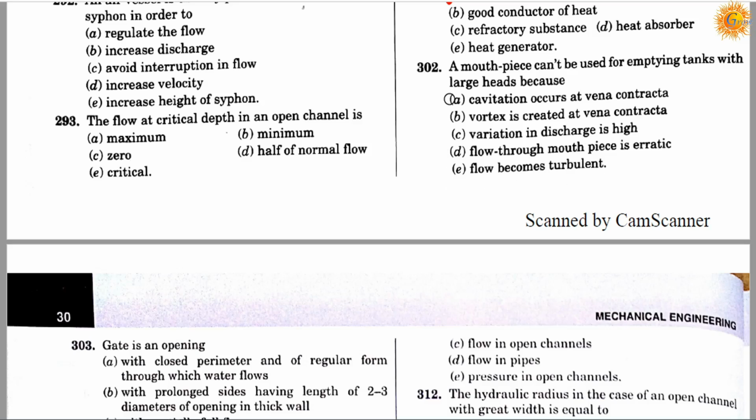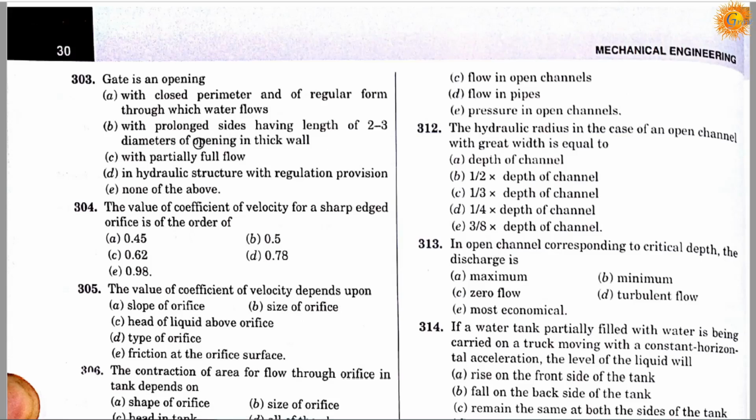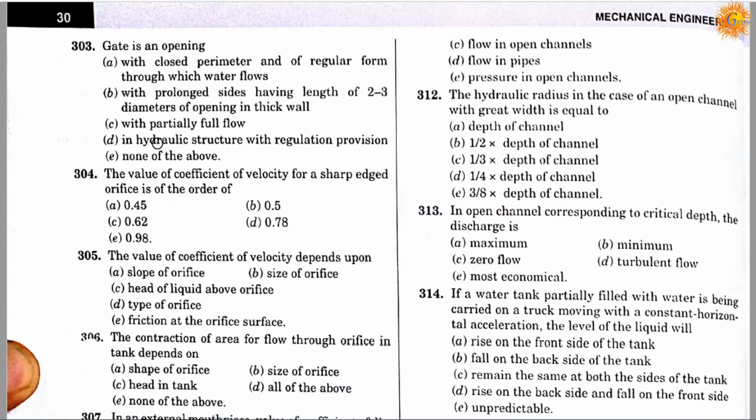The correct answer is A. A mouthpiece can't be used for emptying tanks with large head because cavitation occurs at vena contracta.